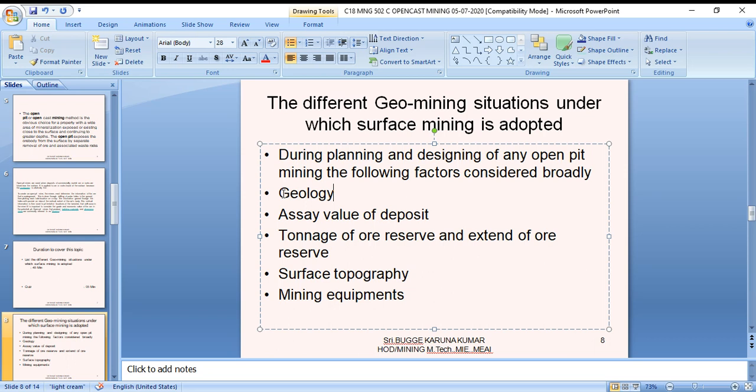That means whether a fault zone is there, any anticline, the structure of the particular rock, its nature and hardness. You have to learn the hardness as well, otherwise you cannot know which machine is applicable. These are the overall weathering properties. Geology is one of the important factors, along with the water nature, the water table and how deep it is. These are some of the influencing factors of geology.